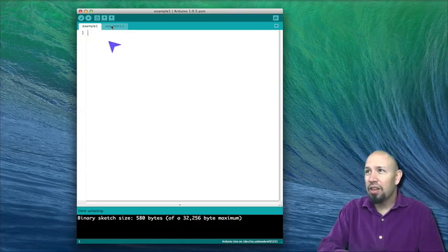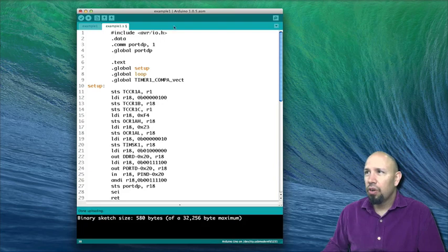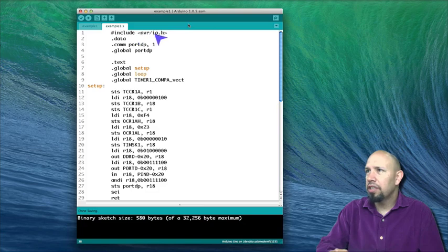So when we use just assembly, we only need really the S file. We don't need an H file either. So go over here to our S file, and so our S file starts off, and in our S file, we first include this H file, this header file, that defines all the I/O ports for the AVR,